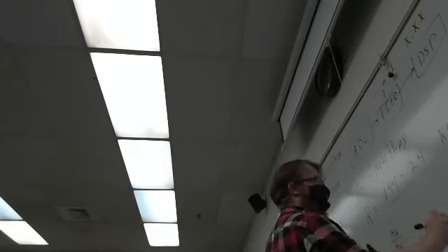Does 4.8 seconds sound good enough? So we think 4.8 seconds. And you can do a really quick sanity check. You could calculate how fast my FIFO would fill up if I wasn't emptying it at all. That gives you a ceiling, right? So you can say, I know it's less than this. If I'm getting 12 kilosamples per second and I have a depth of 48, then I know my maximum is 4 seconds. So that sounds wrong.